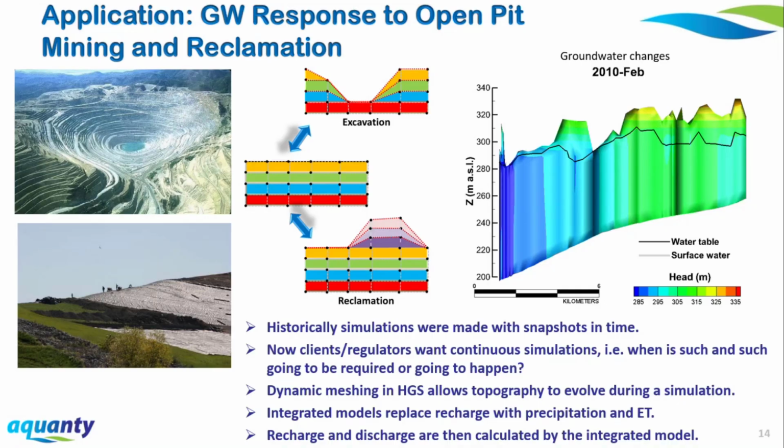So the next application is conjunctive use of groundwater and surface water, where water from one domain is used in another domain, such as surface water being extracted and then injected into groundwater. Just like in managed aquifer recharge, on the cross section on the right, water is being extracted from the surface water body and being injected into an aquifer.